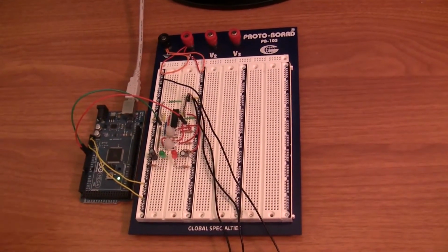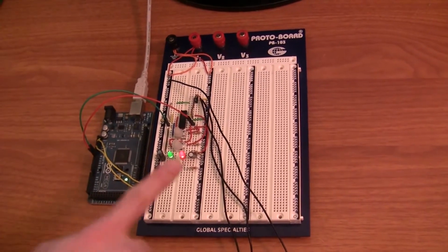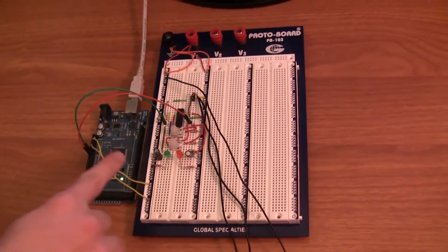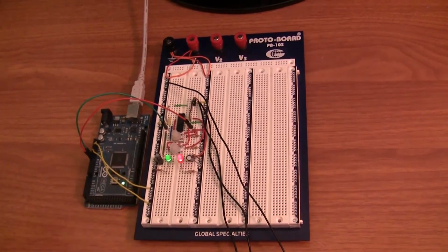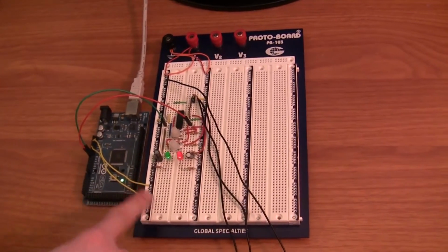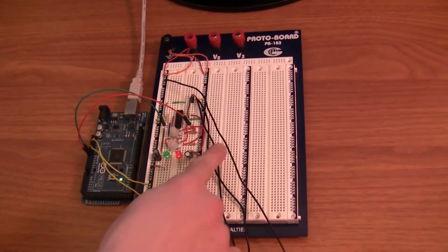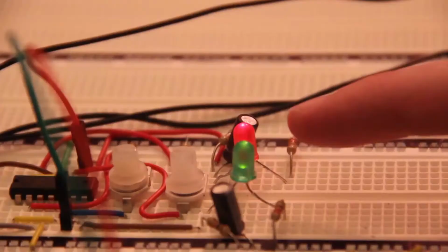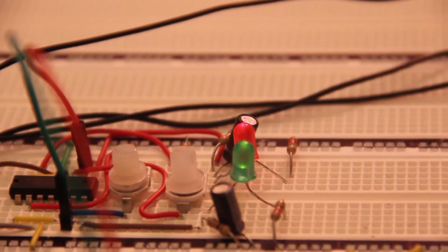Okay, now before you do any programming on your Arduino at all, you should be able to confirm that your amplifier circuit is working correctly. Right now, the only thing we're actually using the Arduino for is power and ground. Basically, it's just a power regulator at this point. So we're feeding in the power and ground there, and we have our headphones feeding into the amplifier system. And we can see that with the music playing in the background, which you guys can hear, the LEDs are blinking in accordance with the current amplitude of the music that we're listening to, which is awesome.